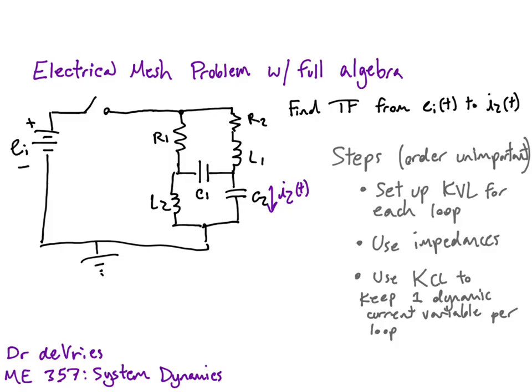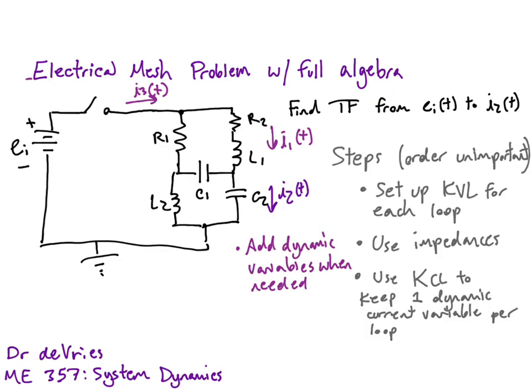Here we only have one defined so far, but if you think about dummy variables, in electrical circuits we're going to see lots of them, in the sense that we want to represent what's going on and set it up in a way that works. So here we have I2, and we're going to add some dummy variables, I1 and I3. We want at least one variable for each loop because that's going to help us solve these problems. We might also want to talk about the current for every single element. So we could give those definitions, name them after the elements they pass through, and then worry about isolating them with KCL afterwards.